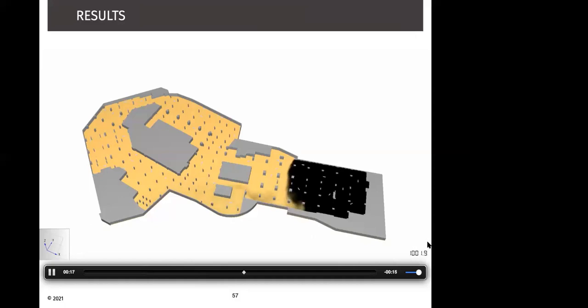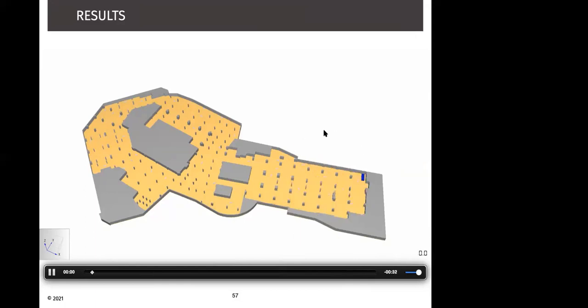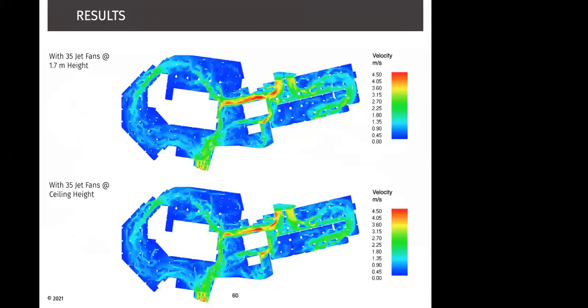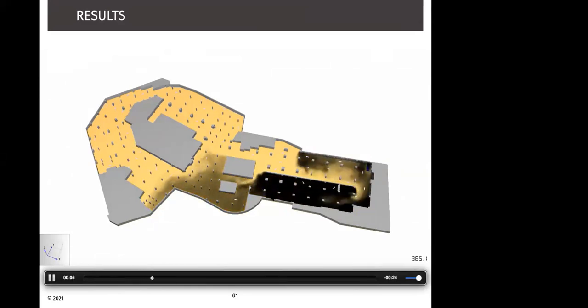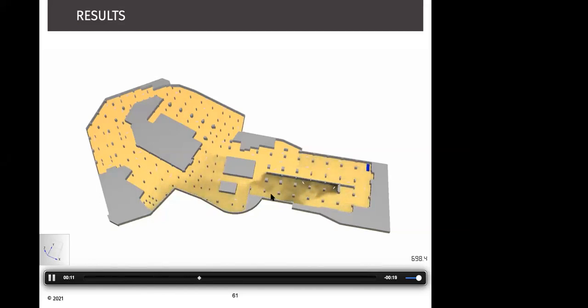So you see that timer over here. This is in seconds. So by 30 minutes, now it's past 20, 25, and now 30. So even at 30 minutes, this smoke is accumulating over here. So that is testing the ventilation system. And once you rectify it, you can again test it to see, with this timer, how the smoke is moving around and whether your system is now evacuating that smoke as you would intend it to. Does that answer the question?